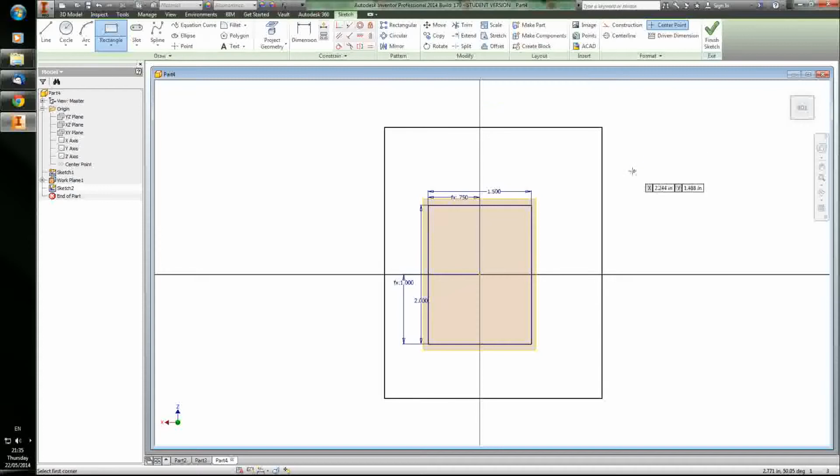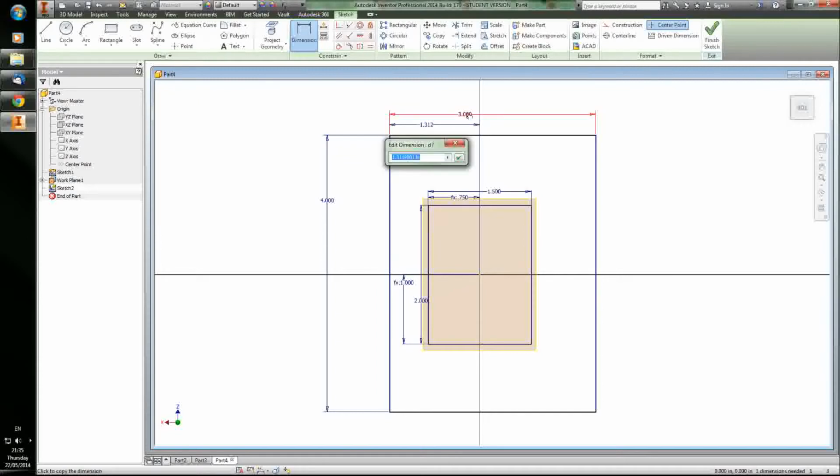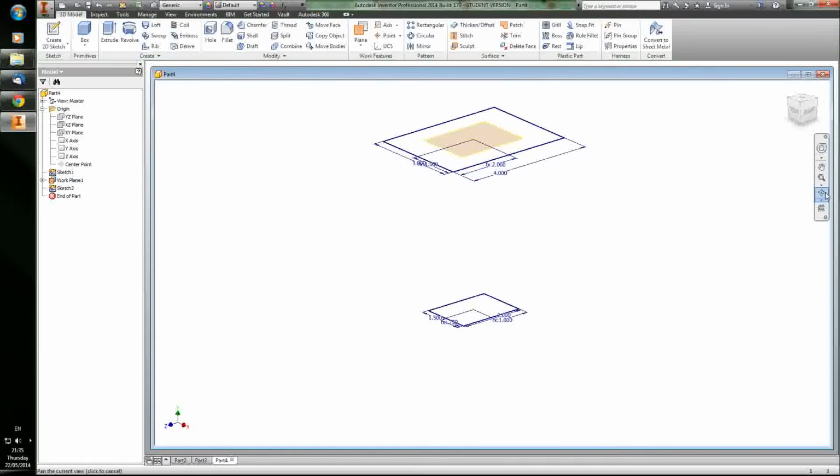And I'm going to create a nice big rectangle up here. And then I'm going to center it. The same origin dot pops up, which makes it really easy. You don't have to project geometry or anything, but you could also do that. So now we've got our 2 sketches.